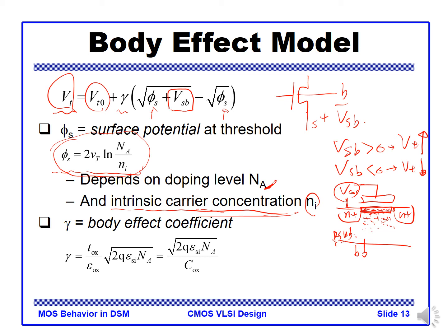So meaning we need more VTH, we increase the VTH with more doping on the channel. We can see that effect in this equation. If you have more doping on the channel surface, definitely you put more doping on the P type here for NMOS. So if you have more doping on the surface, that will increase the Vs, and the VTH will go up, right?